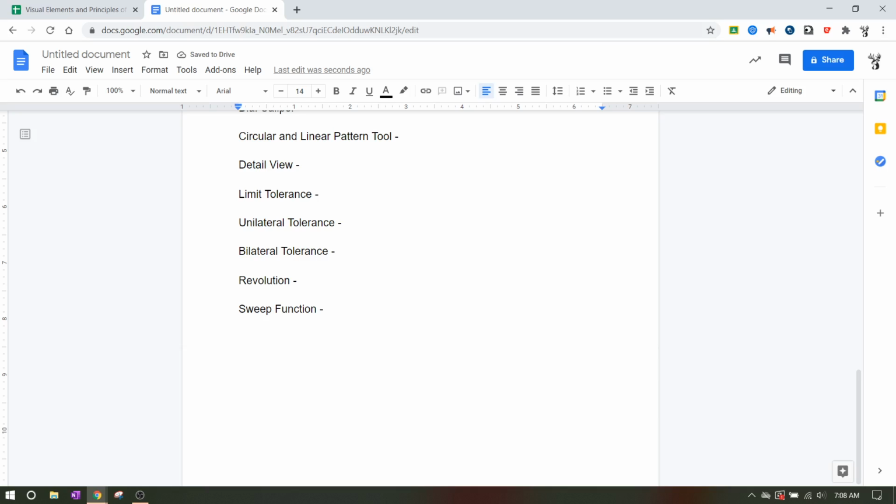The features, let's see here. You need to know the difference between a fillet and a chamfer. A chamfer is going to be kind of chiseled at an edge, and the fillet's going to be rounded, like you took a bunch of sandpaper and put that onto it. You also need to know that we used the bread and butter, which is the extrude command. We use that a lot. You need to know that the fillet command can be done in sketch mode or 3D modeling mode.